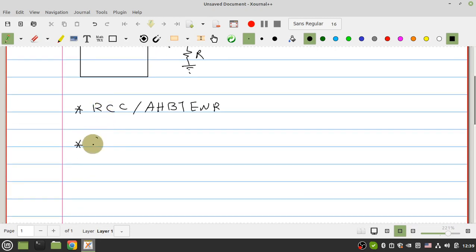After that, in GPIO, there is a register whose name is MODER. It sets the mode of this pin, and I set the GPIO pin as output. You can have some modes in a pin, for example, input, output, analog, or others.